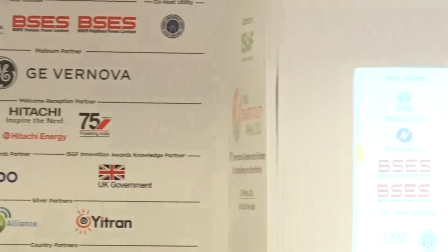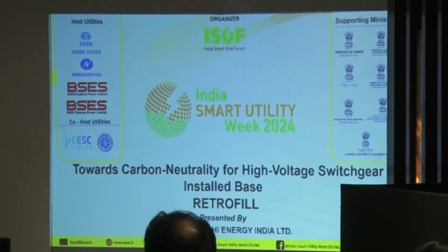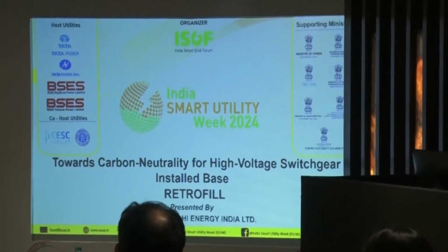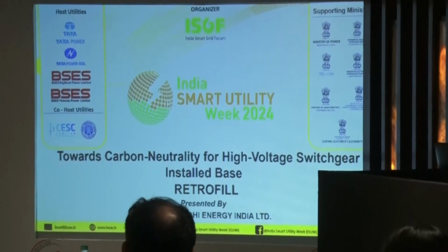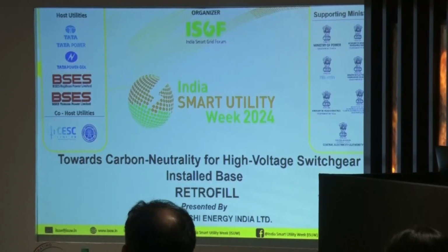In our industry, SF6 gas, which is sulfur hexafluoride, has been a norm for the electrical industry due to its excellent capability in terms of insulation and switching capabilities. However, SF6 is also known for having a high global warming potential, which is a recognized fact. And as we move forward, the impacts on the climate change are more visible. This is where Hitachi Energy plays a significant role, where we intend to develop a portfolio which is SF6 free without compromising on the reliability, scalability, and compactness of the high voltage switchgear.